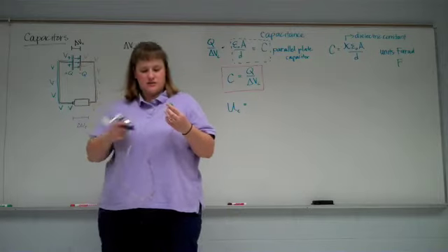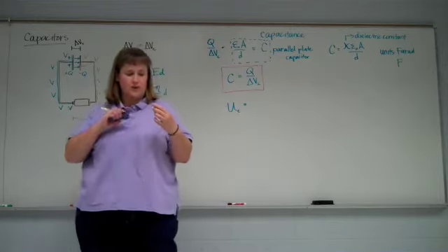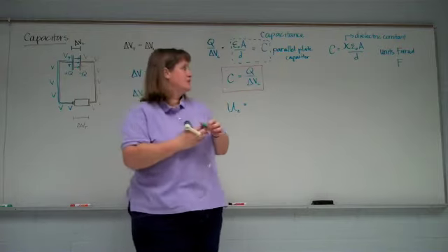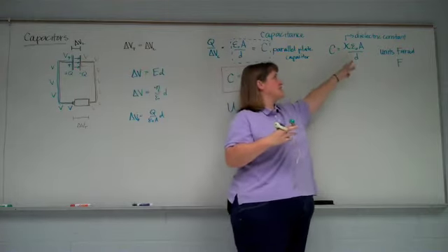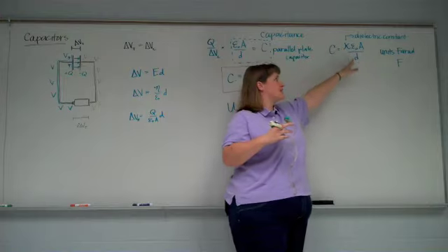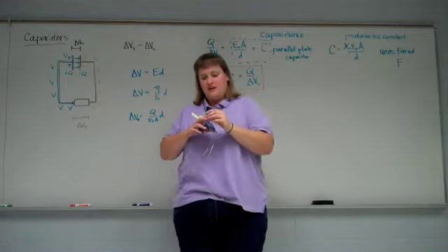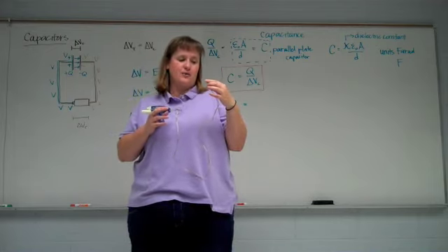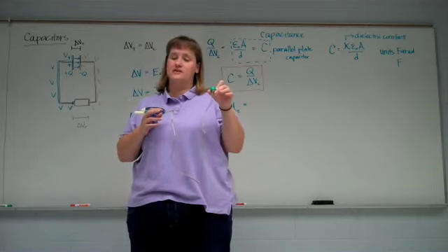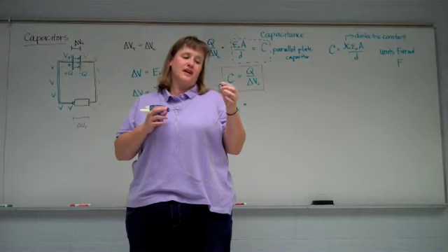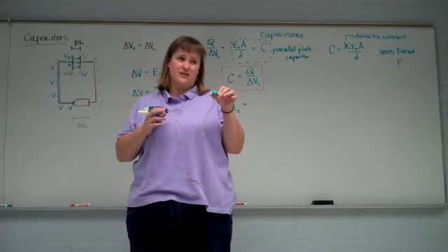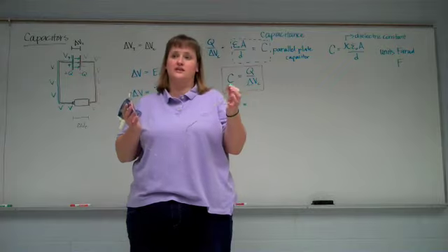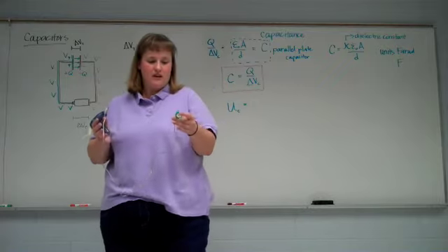All capacitors have what's called a breakdown voltage. So this capacitor is 1 farad. Whatever it's made of, its cross-sectional area, the dielectric between the plates, the distance between the plates, makes it 1 farad. But this capacitor has a breakdown voltage of 5.5 volts. That means if I try to apply anything greater than 5.5 volts to this, I basically blow it up. I ruin it. It's no longer useful, can't be used again.